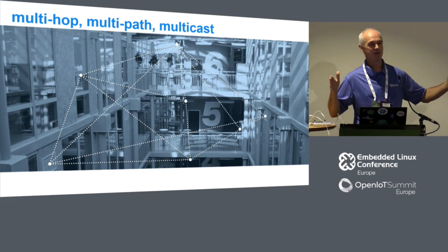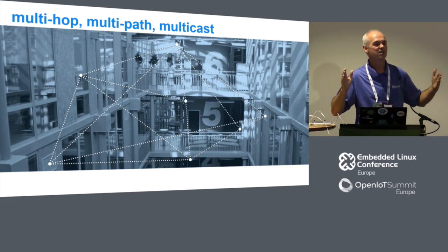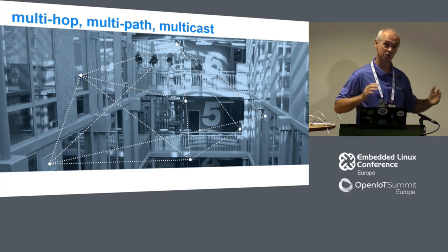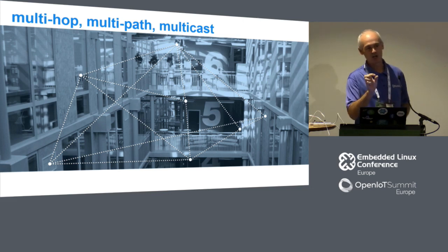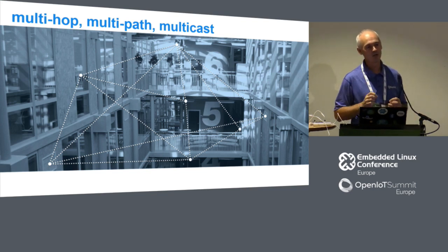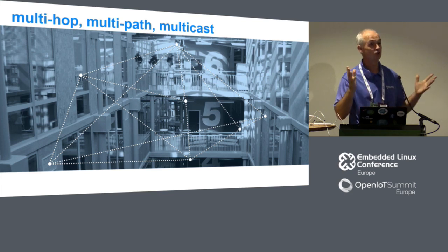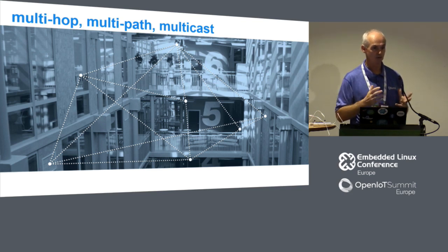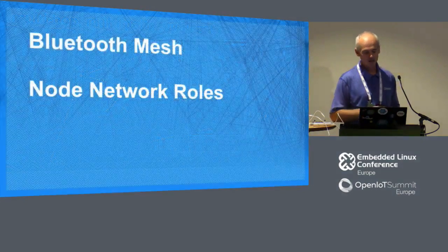Therefore, great big packets to get some job done, on a slow radio, very bad, because you're holding that frequency for a long time. Tiny, highly optimized, highly compressed packets to get the same type of work done, transmitted on the fastest radio going, and Bluetooth is 4 times faster than others. That's good, because you're holding that frequency for a tiny fraction of the time. You'll get a lot done, and because it's a multicast system, one tiny message transmitted in a very short burst could control hundreds of lights all in one go. So it gives you real scalability benefits.